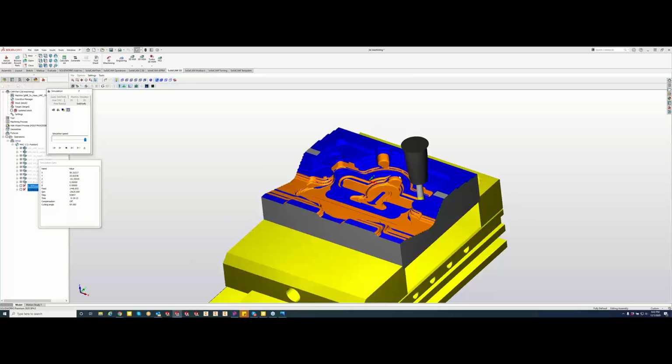And that's one thing I really like about iMachining versus all the other CAM packages out there. A lot of other CAM packages do have a high material removal system. Nothing near what we can do here, but what I've seen from those other CAM software is you don't have control of what you can and can't do. Here with the 3D iMachining or the 2D iMachining, you have full control. We can control, maybe I want to cut my spindle RPM down, or maybe I want to reduce the amount of horsepower required by the spindle using a different tooling. All that, you have full access to the control of that.